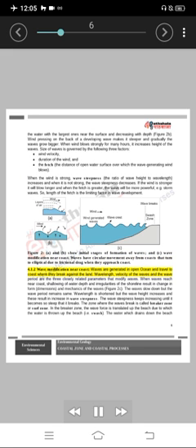4.1.2 Wave modification near coast. Waves are generated in open ocean and travel to coast where they break against the land. Wavelength, velocity of the waves and the wave period are the three closely related parameters that modify waves. When waves reach near coast, shallowing of water depth and irregularities of the shoreline result in change in form, dimensions, and mechanics of the waves, figure 2c.